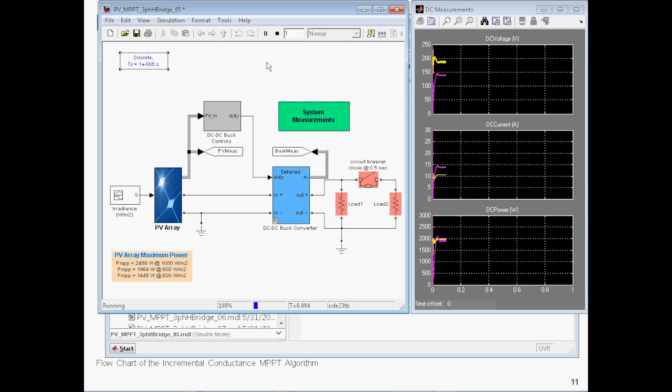So what you do is you design your device, you design your controller in average voltage, you can run very quickly through multiple simulations, and then once your controller is designed, you can test it against the full nonlinear switching simulation very quickly. Notice that I didn't change models. All I did is I changed the subsystem that is being used right now.